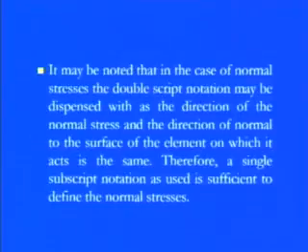Because we know that the nature of the force as well as the domain have the same meaning, and they are working on the same area as far as the area is concerned. So here we can simply judge based on our judgment. It may be noted that in the case of normal stress, the double subscript notation may be dispensed with, as the direction of normal stress and the direction of the normal to the surface of the element on which it acts is the same, as I told you, sigma xx, sigma yy, sigma zz. Therefore, a single subscript is what we are using.